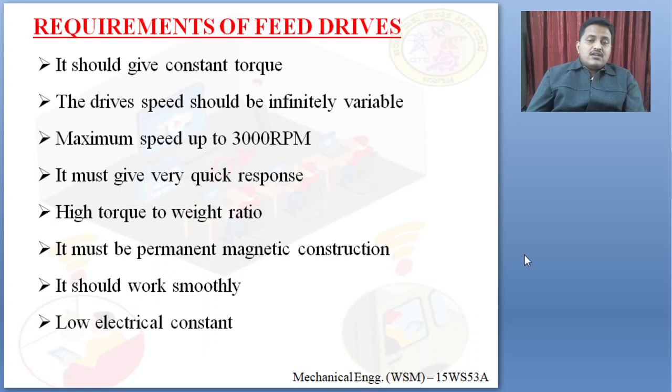Requirements of feed drives. The following are the requirements of feed drives. One such requirement is that it should have constant torque. This is very important, the speed and rotation with respect to force. It should maintain constant torque. The drive speed should be indefinitely variable. This is very important.